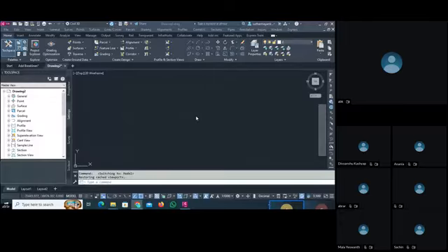Then we moved to Global Mapper where we set current units, assigned elevations, and exported DEM, DXF, and point files. After that, we stepped into Civil 3D where we understood the interface, tabs, and workspace. Then we set the units and coordinate zones. Then we imported the points, checking both the traditional method and the survey tab method. Then we created the line work and surfaces too. So basically from the satellite to the surface model, we completed the full pipeline.